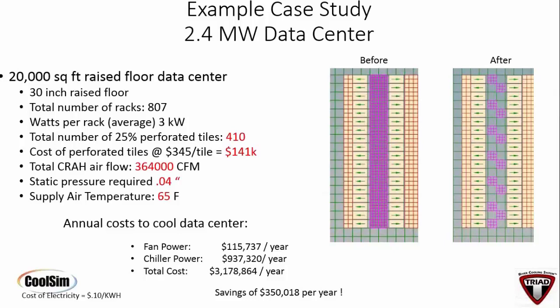you optimize the stratification, the height of the flow, by turning the anterior fin towards the main supply source. As we discussed, this air is moving in all 4 directions. So that will optimize your throw height, your stratification, which we try to maximize at 7 feet. If you notice, our CFM slows down.